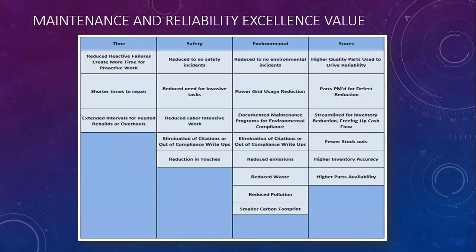All right. And are you using any vibration in conjunction with your ultrasound program? Yeah, we just launched online vibration monitoring on our ammonia compressors. The only reason we're trending bearings now is for precision lubrication with the UltraPro. So we have online systems there, and then we have big mixers and some other large assets that we are doing vibration with.